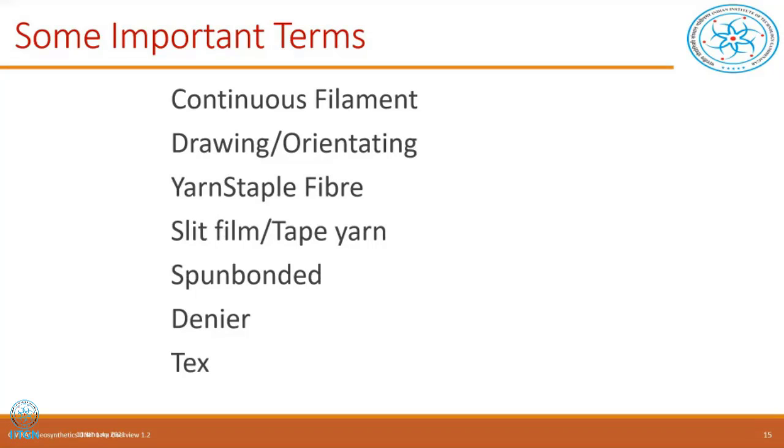Whereas in a natural system, the length of the fiber is going to vary. You take cotton or jute, the length of the fiber is going to vary. It always has a natural crimped shape, and the diameter also will vary from end to end. So that difference is going to be there. Crimping is done because once you start making the yarn from these cut fibers, naturally it has to have interlocking. Otherwise, it's very smooth. So that is why it is called crimped yarn.